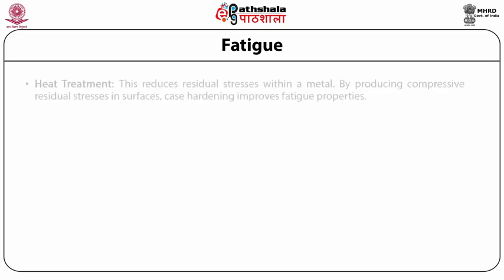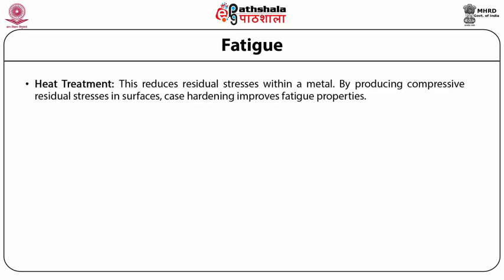Sixth factor is the heat treatment. This reduces residual stresses within a metal. By producing compressive residual stresses in surfaces, case hardening improves fatigue properties.